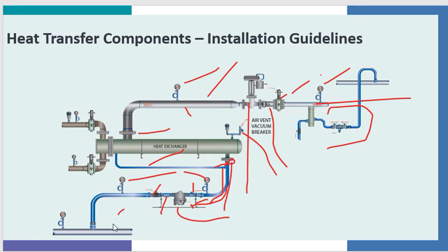Now, the condensate drainage system depends on the operation of the system. There are systems where we can go into pressurized condensate return systems and elevate the piping after the steam trap back into a pipe rack. But there are also a lot of systems where we have to go by gravity away to a condensate pump and be pumped back to the boiler room. Therefore, you really need to know the dynamics of the system.